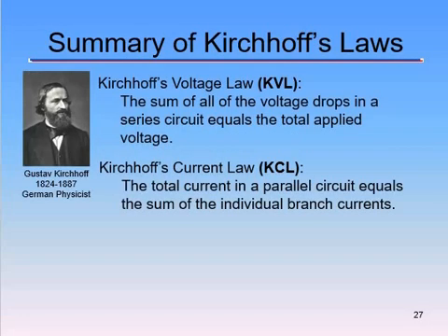So, just to reiterate, Kirchhoff's voltage law, or KVL, we apply that to series circuits only. Make sure you put that in your notes. Kirchhoff's voltage law is series circuits only, and it's the sum of all the individual voltage drops having to equal the total applied voltage. And remember, how did we find the individual voltage drops? We had to use Ohm's law. So V equals I times R in that case, and we found each one of the voltage drops and had to add them up. They had to equal the total battery voltage there.